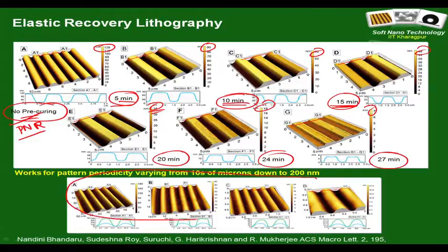You can in fact get similar behavior with long chain molecules even in a glassy polymer, because of the entanglement effect, which I will avoid for the time being. The entanglement of the long chain molecules, even in a glassy polymer, results in some bit of viscoelasticity, and if you anneal such a film for a prolonged time, there is stress relaxation.